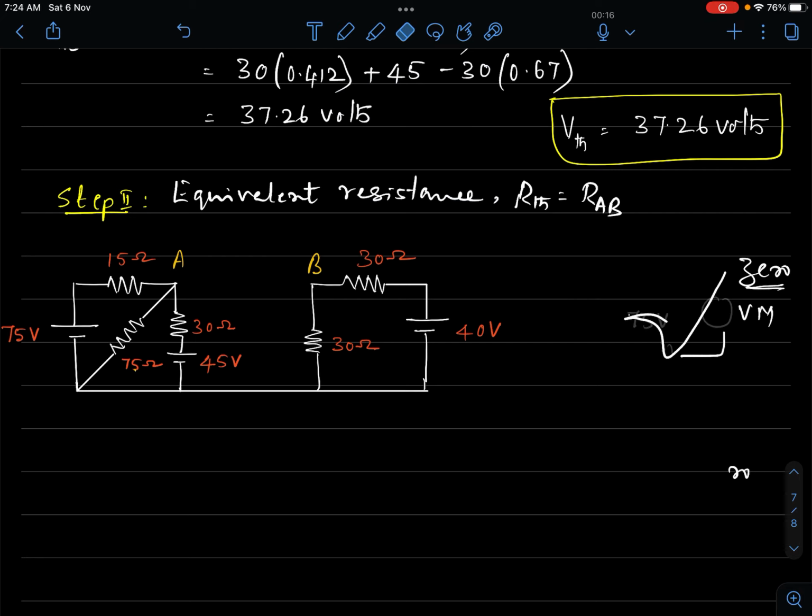So we need to understand this more than remembering this. Switching off condition of a voltage source means replacing the source by a short circuit. That is what we will do. So I will remove this. Wherever there is a source, I have removed the source. The 45 volts is also removed. The 75 volt is also removed. I have removed all the sources.